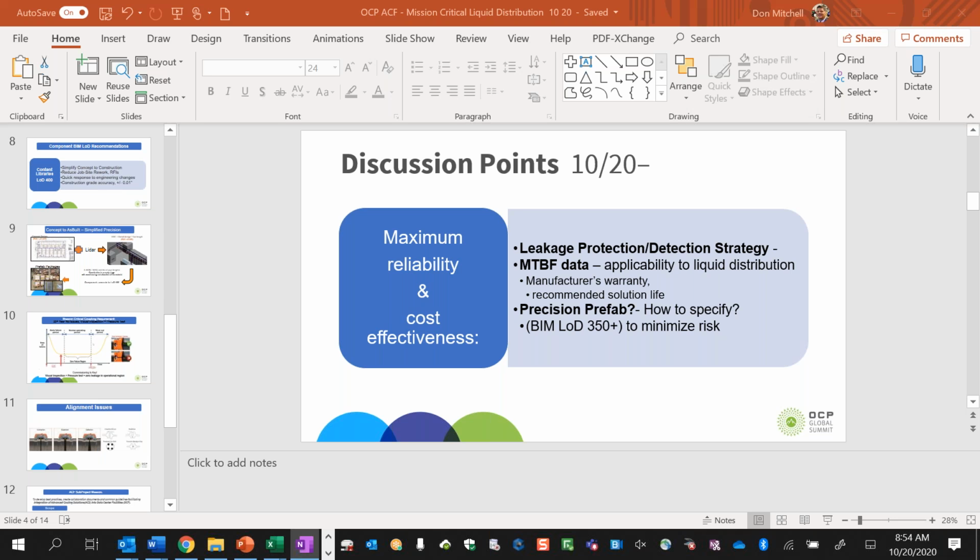Valves generally are not guaranteed for the life of a data center. Do you plan on them? How do you plan around the lifespan of a valve? You generally would have a configuration, hopefully, of N+1, but if you have a single valve that can shut down your system, you probably want to put some kind of bypass loop on it. That would be the most practical way, although if you don't have an N+1. But we did use bypass loops in those critical areas.